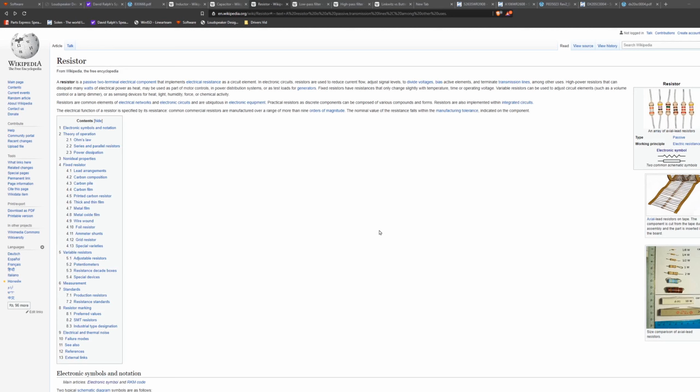There's the amount of resistance that it has, measured in ohms, and then there's the ability for power handling, which is the amount of watts that a resistor can handle. The amount of power that the resistor needs to be able to take will vary depending on the power requirements of the given system. But typically resistors are cheap, so just selecting a 10-watt resistor is usually good enough.